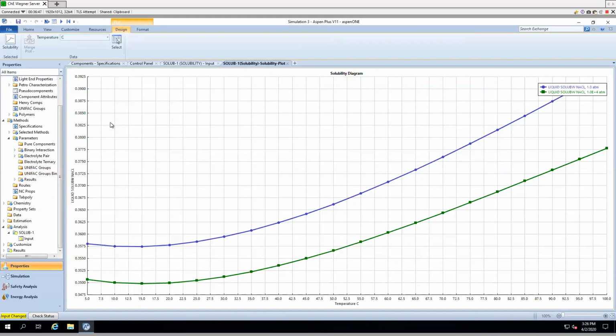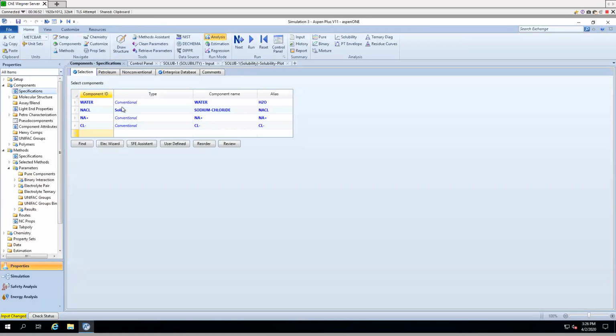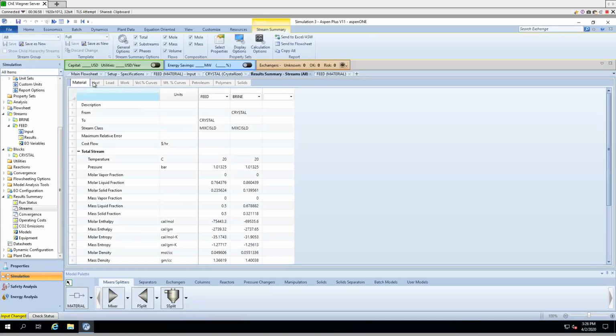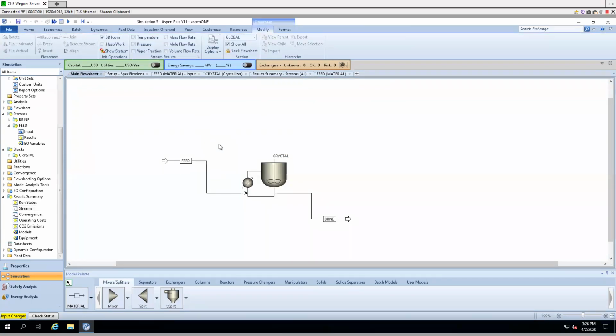Or, alternatively, there is an alternate to this. If you remember back to your equilibrium chemistry, you actually could feed something that involved a chloride ion. But that's a little more chemically inclined than we need. Really, the best situation we could do is just feed less water.